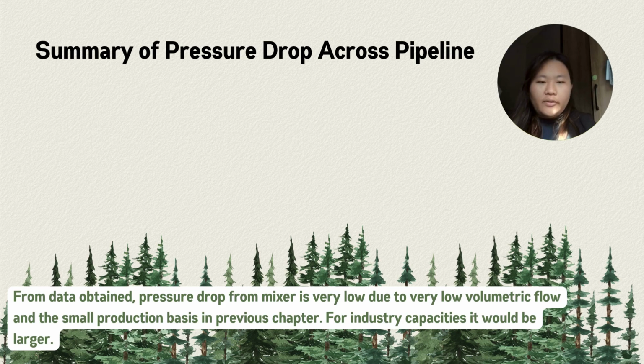So the values are very, very small due to the small production basis. For example, in the mixer to reactor line, the total pressure drop was only 0.023 Pascal, indicating a laminar flow regime. Similarly, the pressure losses for other pipelines were found to be extremely small due to the very small production basis and also the pilot scale production.